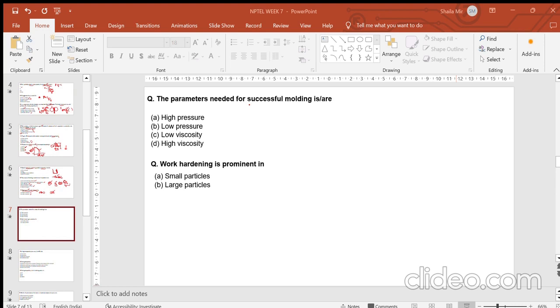Just a second. Hold on. That is (NC minus NO) divided by NO. Yes, that reference at the denominator NO is taken. Why not NC at the denominator? Because we are just trying to see that the critical speed is 40% less than the operational speed. If the operational speed were less than the critical speed, then we would have taken NC, because the reference is the critical speed. The critical speed is 40% less than the operational speed. That is why I have taken NC.